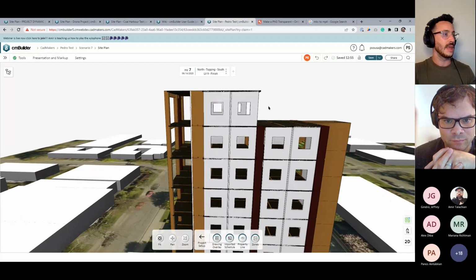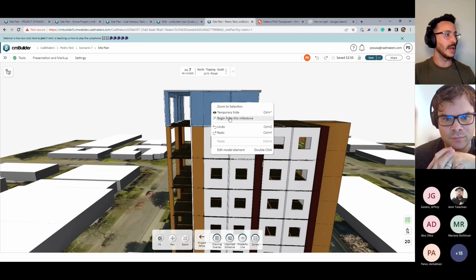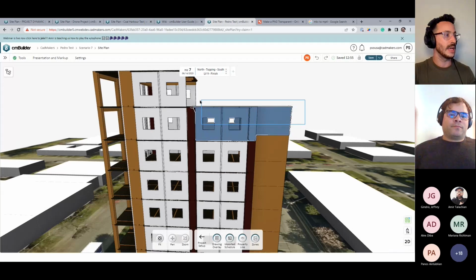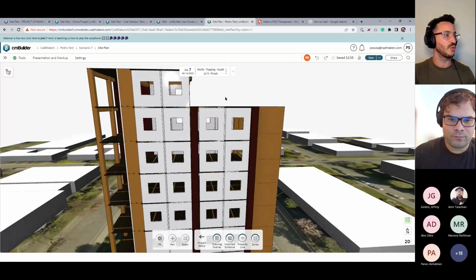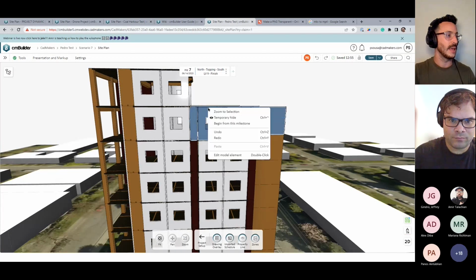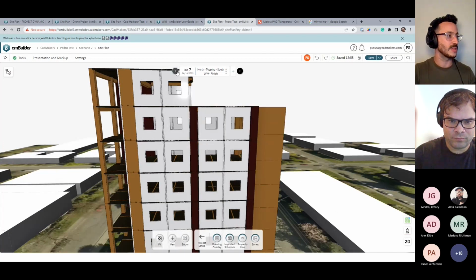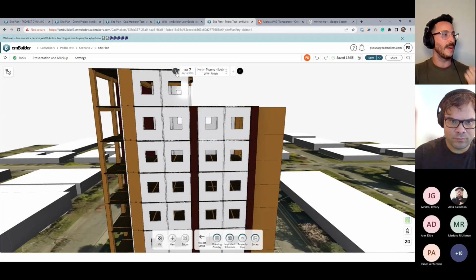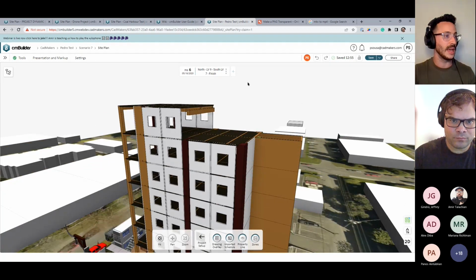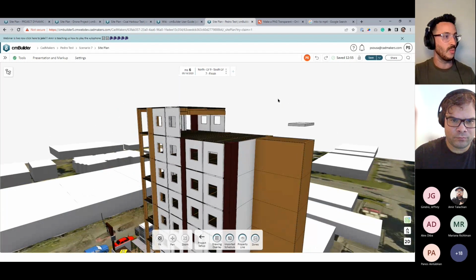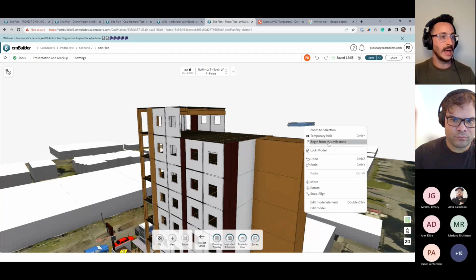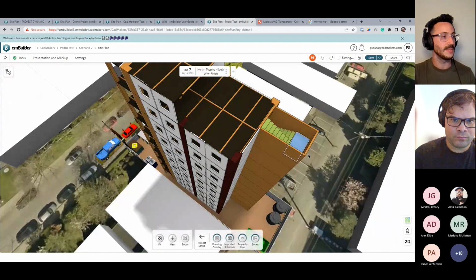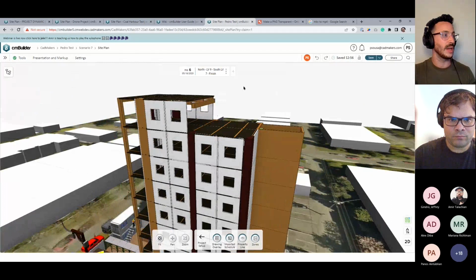So I'm going to assign the last part over here to this milestone, and the south all the way to level 9 as well. You can hold control to do a lasso selection and then have these begin from this milestone. Now if I go back and forth, you see, because I assigned those parts to that milestone, if I go back, those objects haven't been executed yet, right? So I can easily visualize what's going on over here. And this guy actually has to start at this milestone. So I can quickly do that kind of stuff.